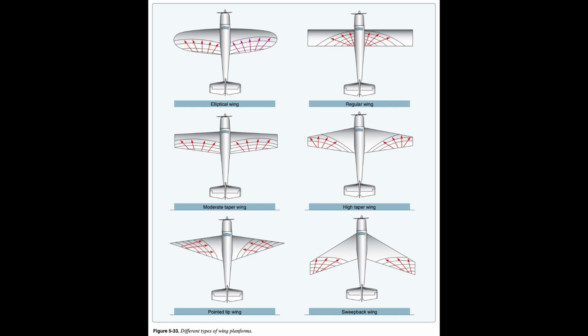It should be noted, however, that with an increase in aspect ratio there is an increase in the length of span, with a corresponding increase in the weight of the wing structure, which means the wing must be heavier to carry the same load. For this reason, part of the gain, due to a decrease in drag, is lost because of the increased weight, and a compromise in design is necessary to obtain the best results from these two conflicting conditions.